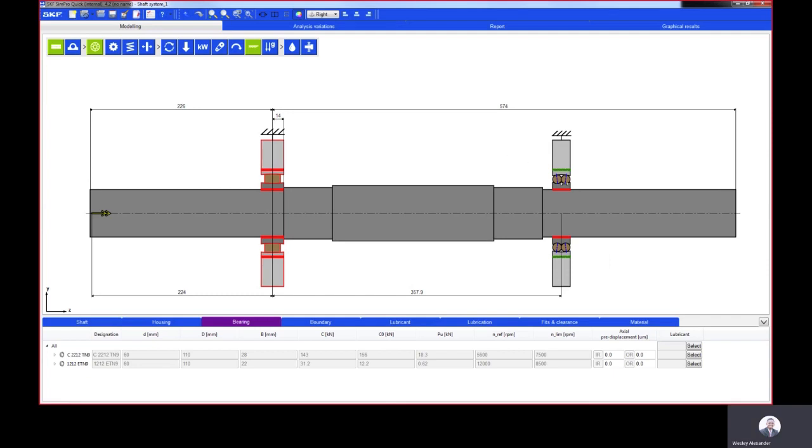When your bearing is axially free, it will be able to slide inside your housing. But because we're using a CARB bearing, that sliding takes place internally. And the sliding is necessary to be able to accommodate thermal expansion. So in other words, that's the free bearing, and this is the fixed bearing.